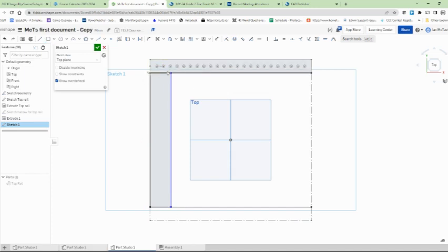With the escape button, that prevents me from adding in the dimensions, and I wanted to show you different ways to do this. So one way is you just type them in as you do it. Now, I'm likely to get an error that way because it'll over constrain it, because I'll be trying to set this length, but this length is constrained by the distance from that point to that line. So if I try to set both things, then it's going to be over constrained and I'll get red.